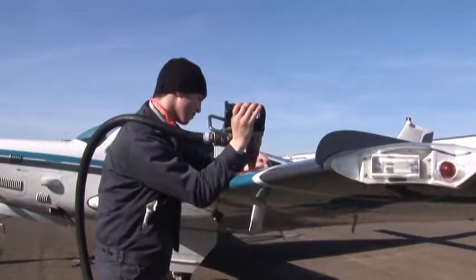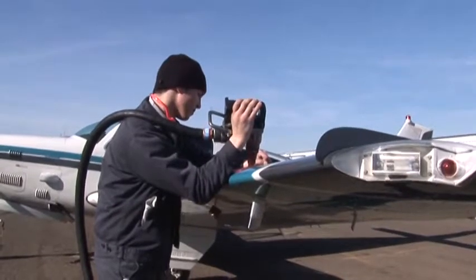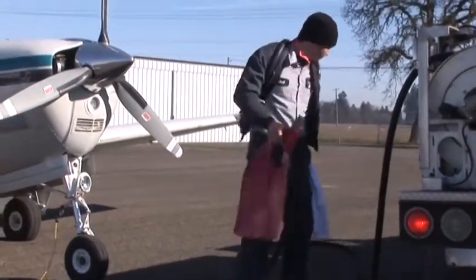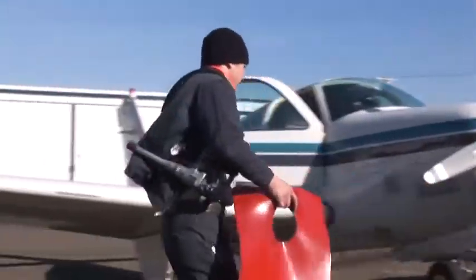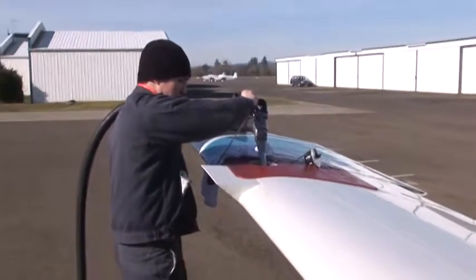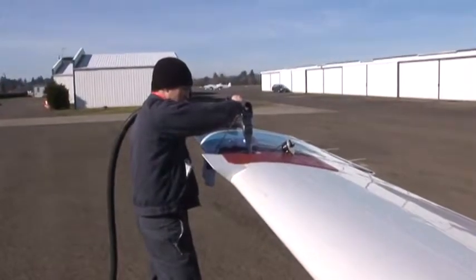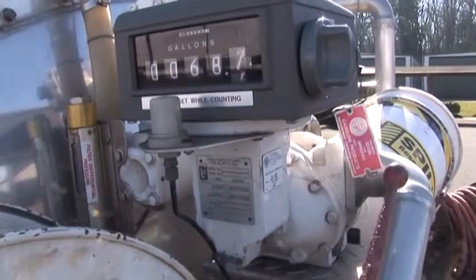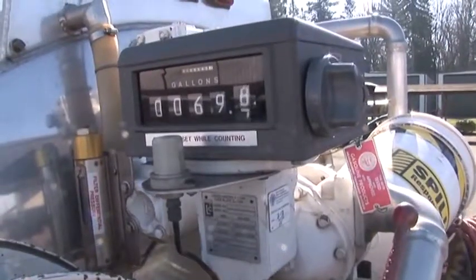Engine fuels are available in different grades or octane ratings coded by distinct colors. Aviation fuels are color-coded to make it easy to tell the fuel rating and type. Now, if you sump your fuel tanks and find red fuel when you normally see blue, you know you've got a problem. Let's take a look at each fuel grade individually.